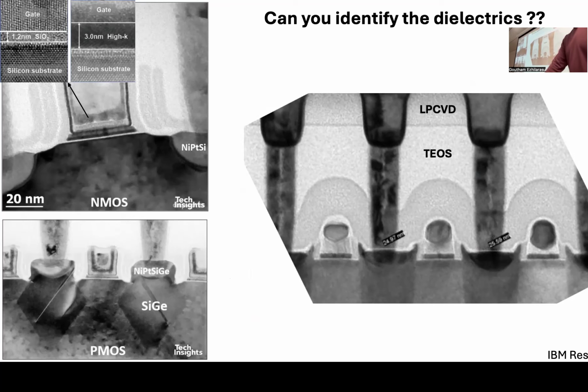But the general trend is that when you make the dielectrics even lower K, they tend to be more mechanically unstable. Most of these dies are eventually going to be packaged, which means you're going to do some bonding, right? When you do bonding, you take the die and apply pressure. If the dielectric is not able to withstand that pressure, it's going to get damaged. So you can't go very low K. You basically do enough to get the benefit. The main reason why you want low K is to lower the RC delay of the links, right?